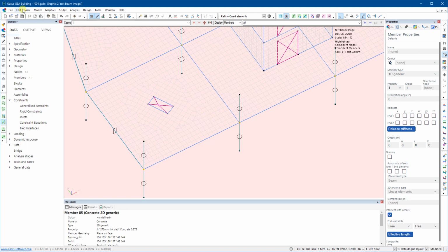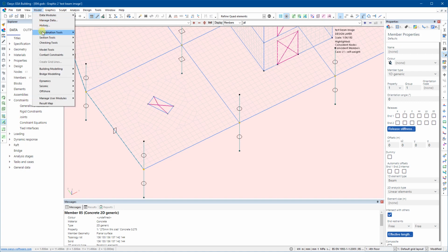So you can do that after you've created the mesh in the design layer. The only issue there is once you've created the mesh and you've started to work on that mesh, you can't then delete the mesh and alter things in the design layer without essentially deleting all the work that you've done. So that's the compromise. But I'll show you the process anyway.